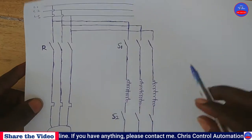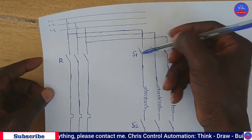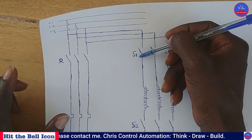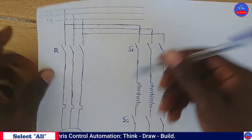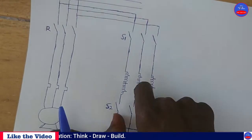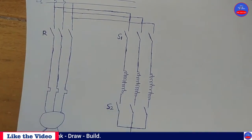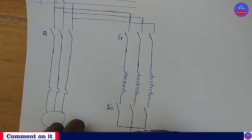After that, the start contactor will also close. When it closes, the 415 volt is applied to the 3 windings, and we star this side together. So this side becomes 0 potential, 0 volt.